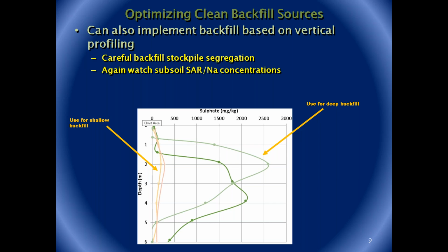And like I said, you have to do some post modifications in Excel because the sulfate guidelines are different for different receptors of concern. But you could actually determine if there was a sulfate risk associated with that backfill material and potentially use it if you're stuck in a situation where you can't get this good low EC salinity material that'll cover all of your excavation. And so there are some cost benefits there. There's some costs on the upfront side and the additional investigations, but a lot of times the backfill EC can drive your excavation depth. So you can have a lot of savings that counteract that.